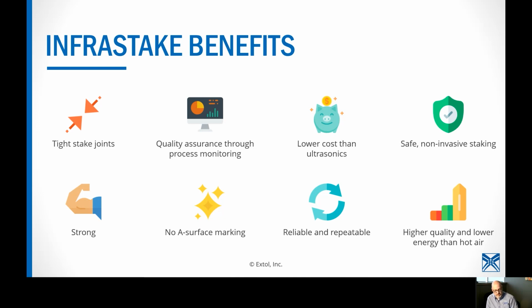But there are also sensors within the system that will tell you when your stake is not complete, which basically means we've put some energy into the part, but not enough, which will be a big indicator that your lamp performance is starting to degrade. And it's important, some plastics are more susceptible to degradation than others. Polypropylene, for example, you'll be able to stake a lot longer on an old lamp than you would maybe a nylon or something like that.